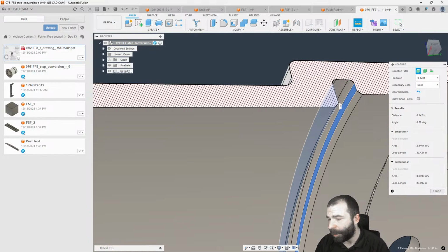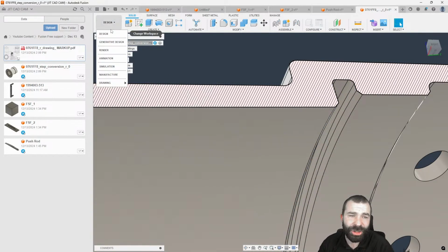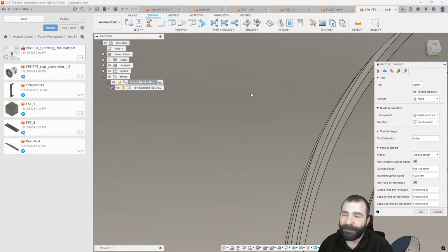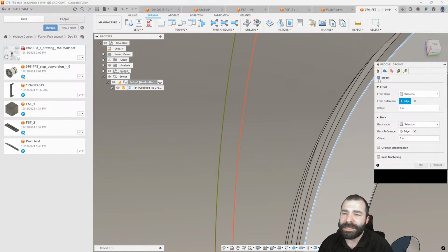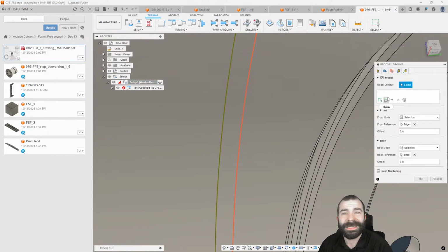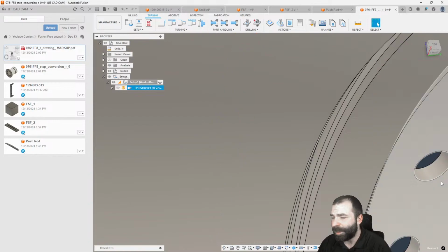So I hope that helps you a ton with, who was it that asked that, Brandon? That's a little different way. I know it takes a little bit of modeling, but by forcing the model, it tends to help you longer in the toolpath. There is also the third option, which is a sketch. On a lot of the toolpaths inside of Fusion, now you have that ability to use model and actually use a sketch that you created. And I know a lot of people that do that well.